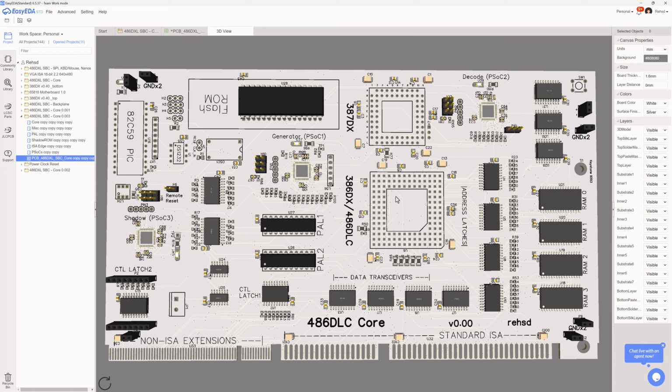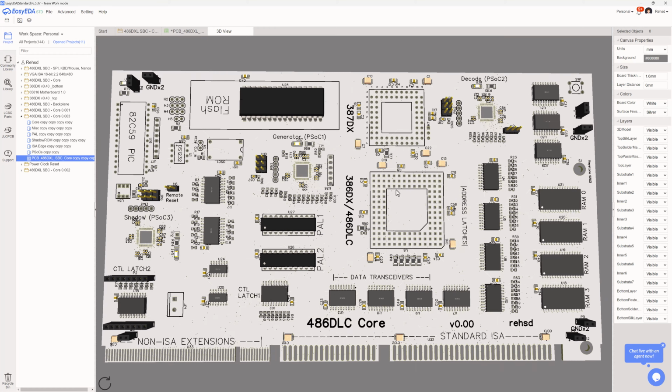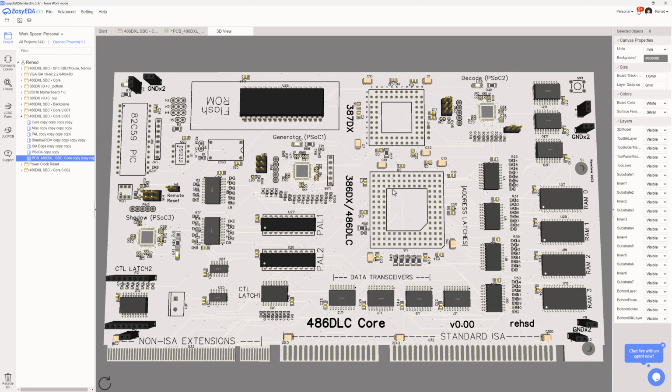I'm sure that's a possibility and people do that, but I'm probably more comfortable if it is all on one side, so I can set this down on the hot plate and do all the work on the top side. And that's both for the assembly and also for the ongoing work, if I'm going to have to pull a chip or do something, I want to be able to get to all of that stuff on the top for the most part. I did try it. I did do some layouts with it and just didn't get to one that really jumped out as the right way to place things on the back side.